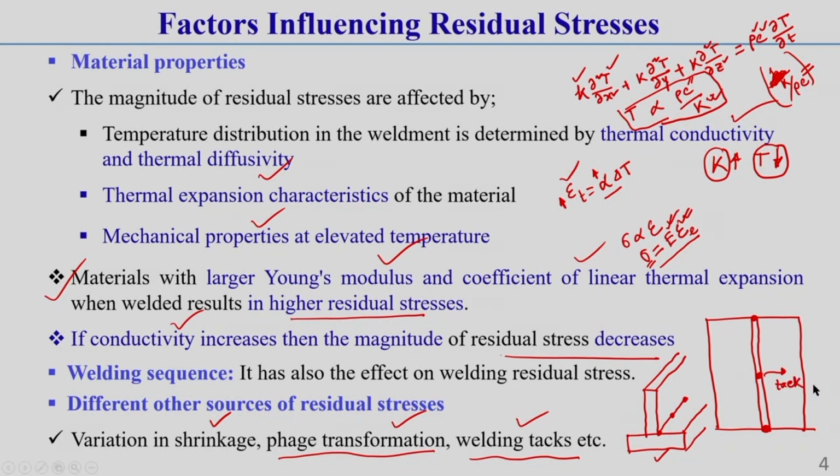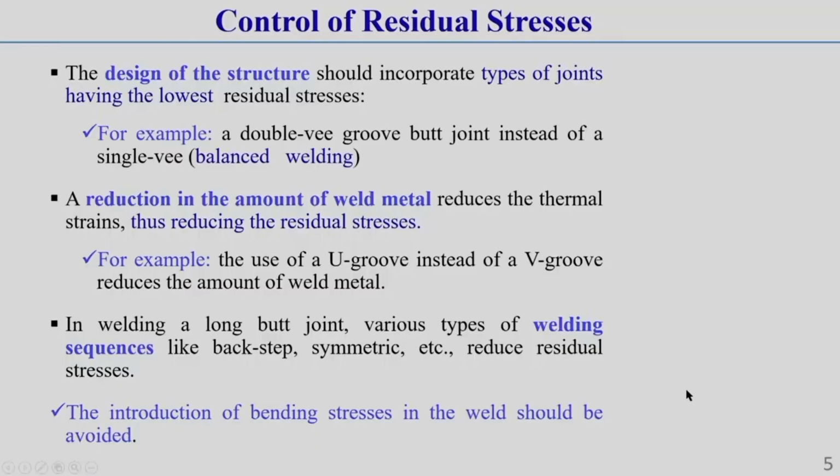Generally during the welding operation, there is a chance of cracking this tack due to expansion and contraction phenomena during the heating and cooling cycle. This cracked tack is a huge stress riser. That is why, once we go for doing the welding, first of all we have to remove this tack, or you can say cracked tack, by using melting or some other removing operation. Okay. This you should keep it in mind. These things I have written in a subsequent slide that I am just showing.